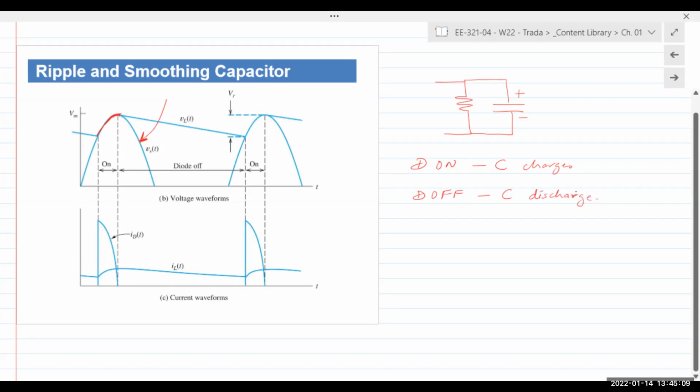Remember first order transient circuits, chapter 4 from E201, charging, discharging, right? What controls or what describes the speed of charge and discharge? And time constant is R times C, right? R times C. And the speed of charging and discharging does not change, remains the same. So if you're charging a capacitor, it still is product of R and C. When it's discharging, it's still a product of R and C.